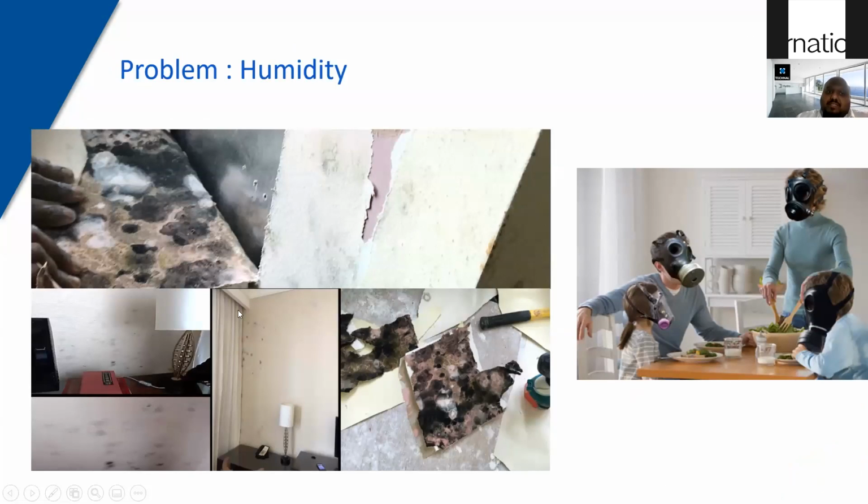And this is a picture from a hotel. I would not name it, but as you can see, this drywall system is connected to the mullion of a curtain wall system, which has been having condensation issues during every summer to winter transition period. And as you notice, these black spots are nothing but fungal growth.